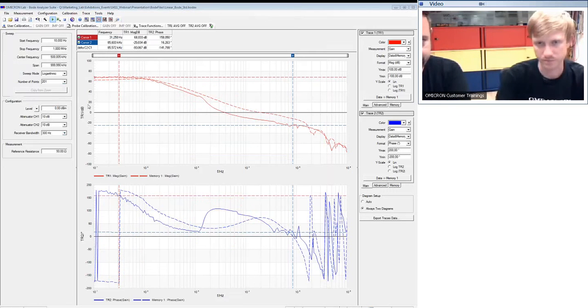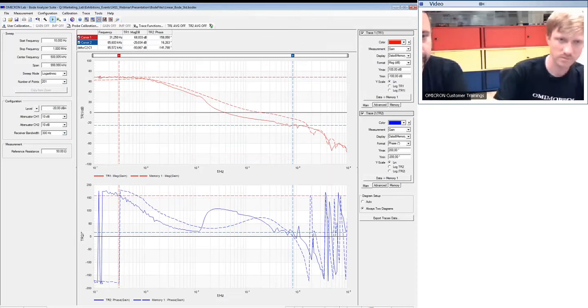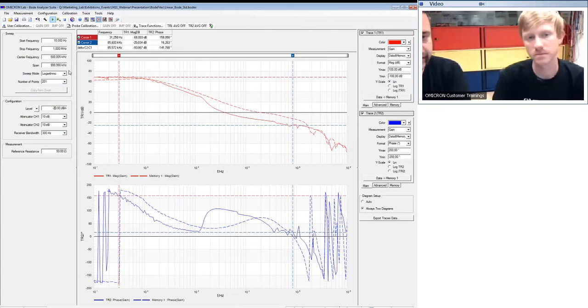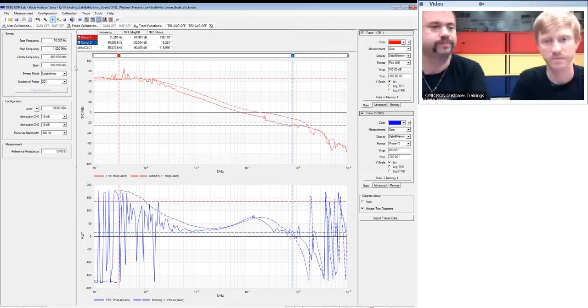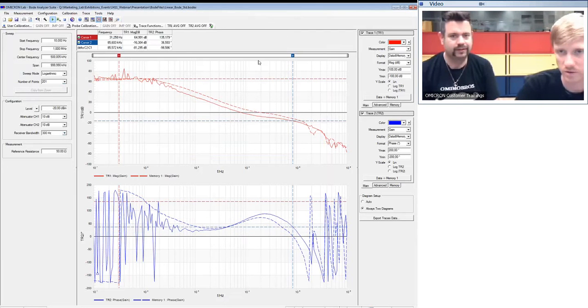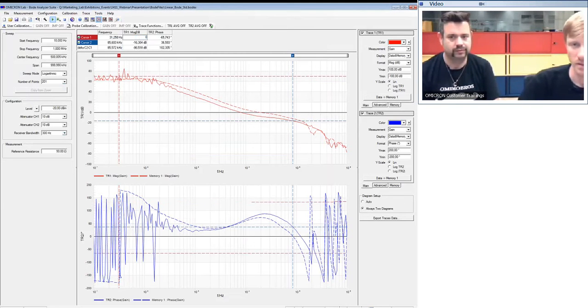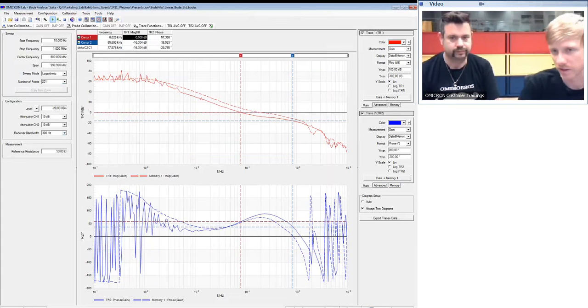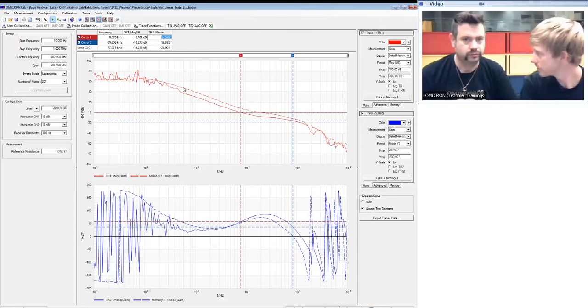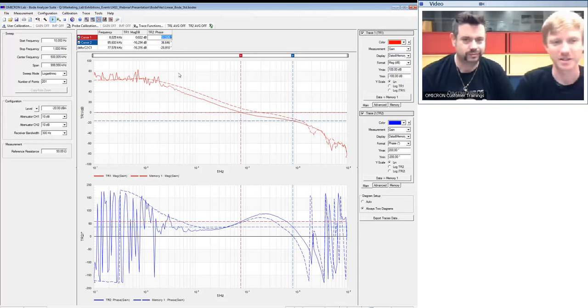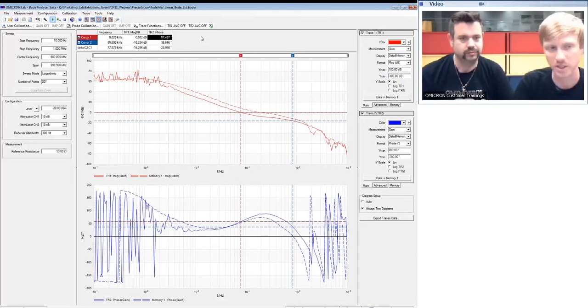And now, what we will do is we reduce to minus 20, and we check if the minus 20 we used before is enough for this measurement, or if we have to go lower. Okay, so I'm searching the crossover point again by entering 0 dB here at the cursor 1 and pressing enter, and we see that the crossover has moved towards 88 kilohertz, so the system got slower, and the phase margin is less now. It's 57 degrees, so it means less phase margin and a slower system.